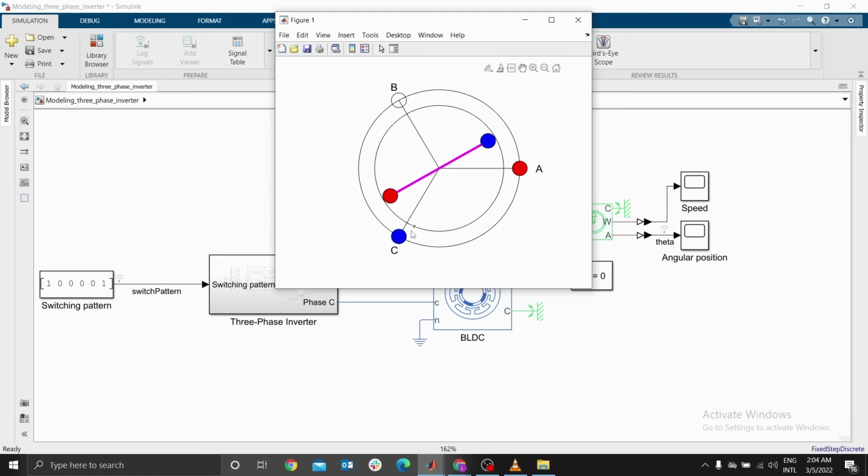In our next video, we are going to energize B with A, and change how we energize the stator windings. In the process, the rotor will start to spin. As you can see now, it has just spun and stopped, because the type of switching pattern we have is called a static switching pattern. We are just applying voltage continuously to the stator windings of A and C.